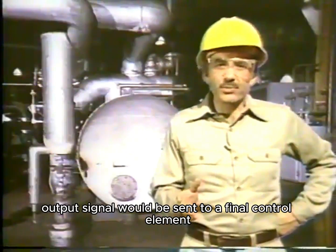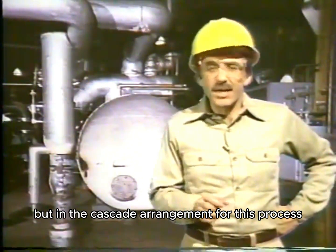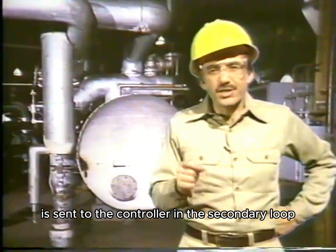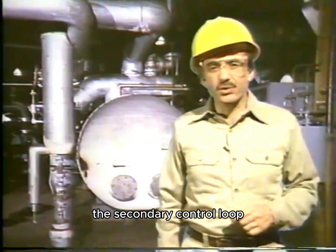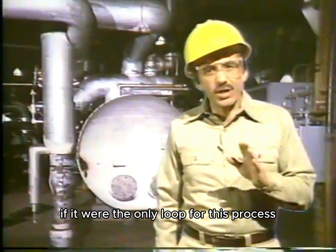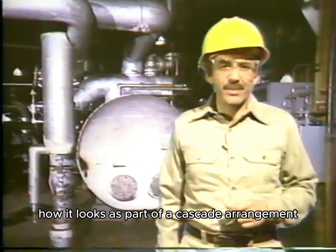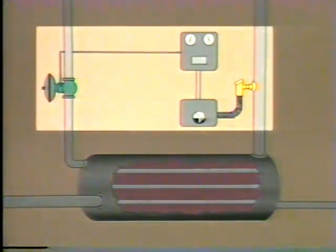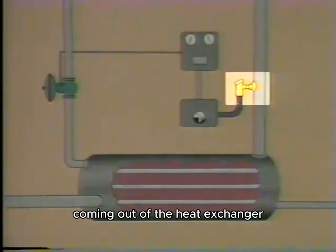Normally, this output signal would be sent to a final control element, but in the cascade arrangement for this process, the output from the controller in the primary loop is sent to the controller in the secondary loop. Now, we'll see how this is done when we look at the secondary control loop. But for now, let's see how the primary control loop might look if it were the only loop for this process, rather than how it looks as part of a cascade arrangement. What we have so far is a single element control loop. We're monitoring one variable, the temperature of the water coming out of the heat exchanger.